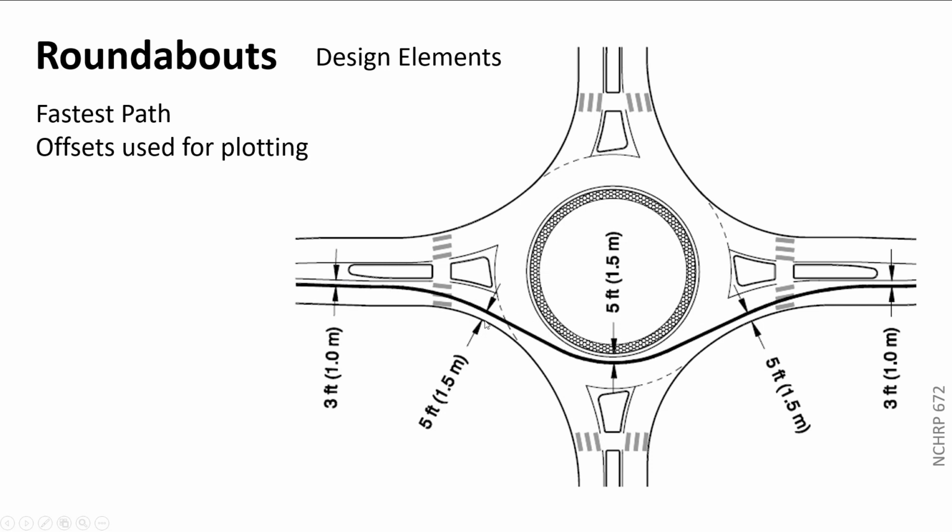They come out here. They'll get about 5 feet from the edge of pavement. People are a little more worried about hitting the edge here, and there's usually curb there, and that scares them. And it's the far side of the vehicle from the driver. And then here, they'll be 5 feet off that island, then 5 feet here, and then back to 3 feet here, because this is just a striped line. They'll get closer to a striped line than they will a hard object.